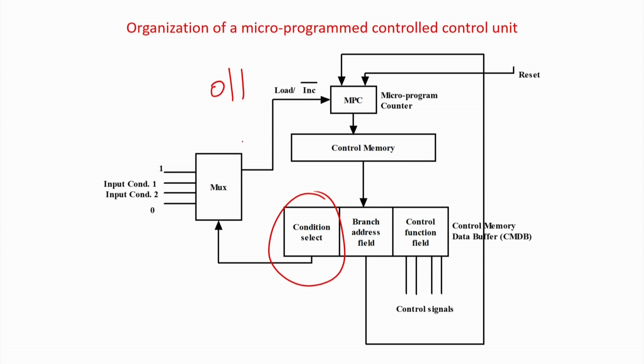So, for that they are actually having a multiplexer based implementation. You can have any other implementation, they have a microprogram based implementation. They say that, for example, I have only 4 condition codes, so you have a 4:2 multiplexer, as simple as that. If you have many conditions to be checked, that is going to increase. So I say that there are actually only 4 conditions which have to be checked.